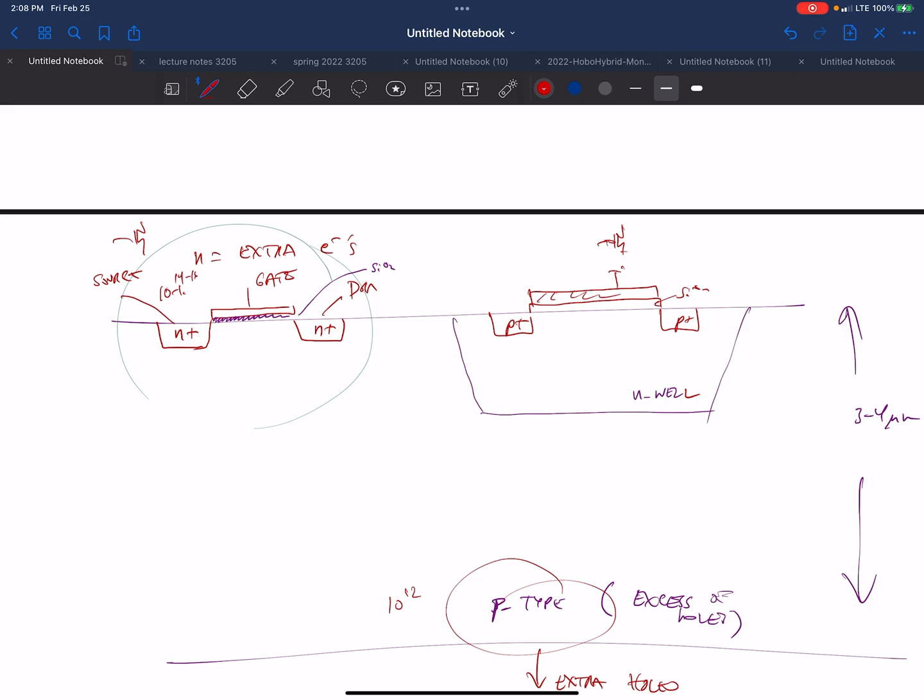Normally, say we have a wafer, and then we process that wafer. Most of the time they're N-wells, right? No, they're P-wells? Well, it just depends on what you make. But normally you would do N-wells on a P-type material. And then you would just convert that N-well into a P-well? No, you would just put P-wells here.